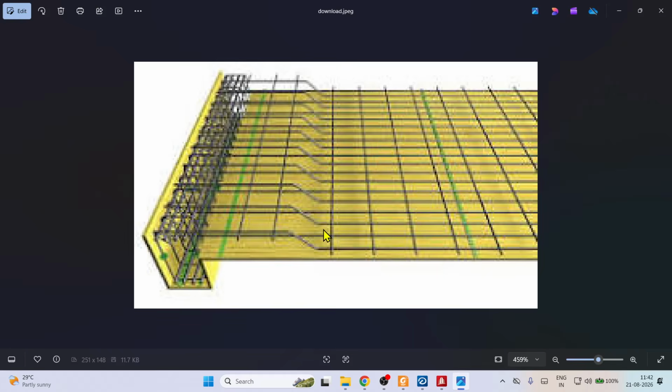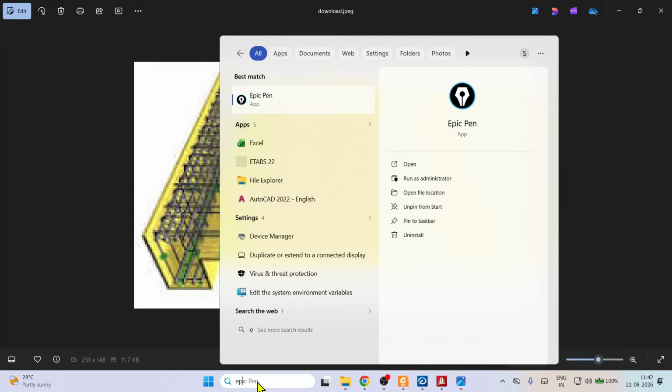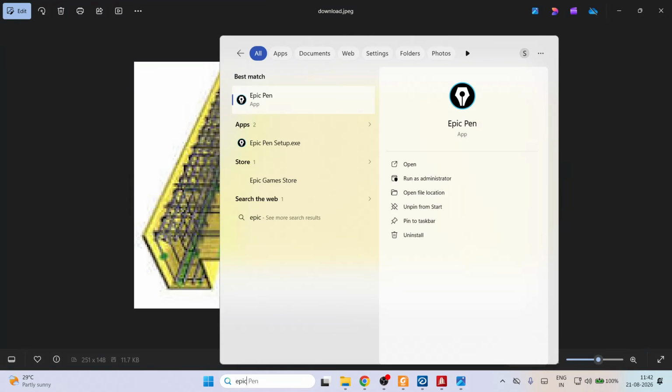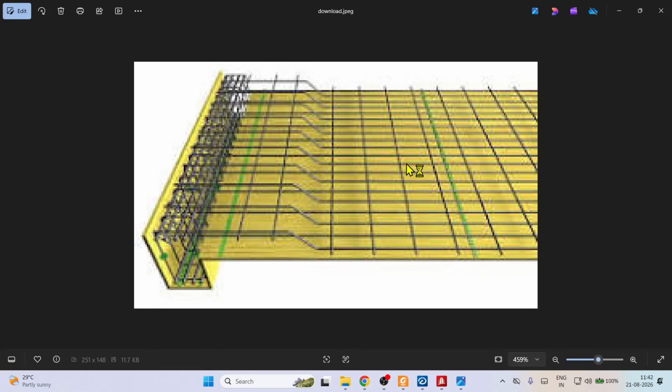When you are bending the alternate bar, and one bar is also going to the end, you have to provide extra top on it. You have to provide this extra top like that. Here it's gone, it's this bar, so you have to provide the extra top. Again you have to provide this bar like that.